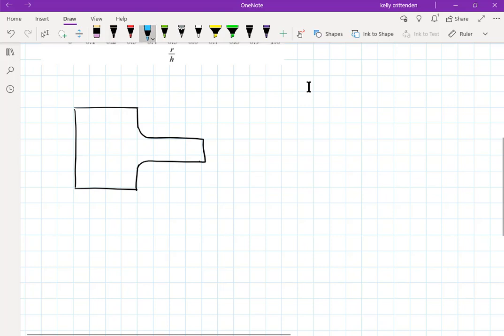So you've got this plate. It has some thickness that we're not concerned about at the moment, but its thickness is into the page. We're looking at it kind of over the top. This will be 4 inches here, and it reduces down to 2 inches over here. And this feature is called a fillet. It's spelled like fillet, but it is pronounced fillet. And it's basically a transition so that you don't have a sharp corner there. You know, you could have this shape, right? You could have this, and you have that sharp corner right there.